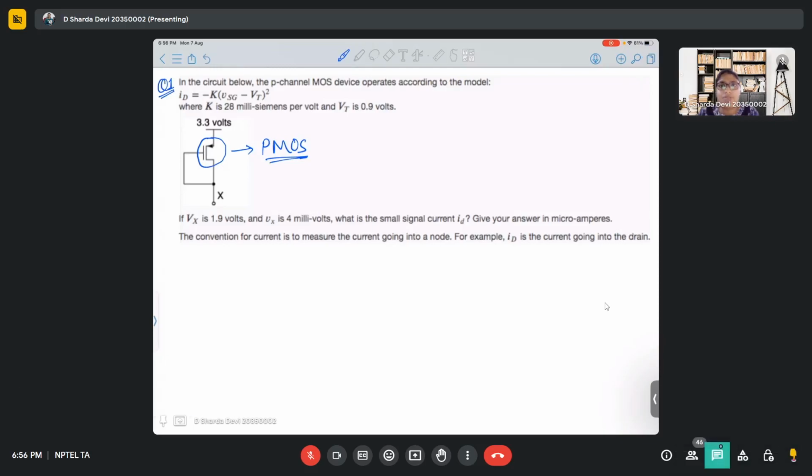Ideally, it depends on how the transistor has been fabricated. Is there any constant value that the threshold voltage should be around? I'm asking from that point of view. See, it depends on what MOSFET you are using. Generally, if you look into the data sheets for that particular IC that you are trying to calculate, there you can find the value of VTH, and how you will check whether you have attained your VTH or not.